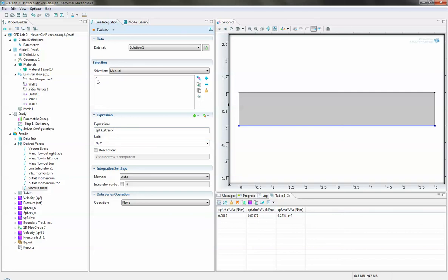So we've got that, and which direction is this acting? If the flow is coming in at this boundary and exiting that side, yes, the viscous shear actually acts to push the liquid in the opposite direction it's flowing. So it's an opposing force on the plate, on the fluid as the fluid goes across it. So I believe we have everything right.